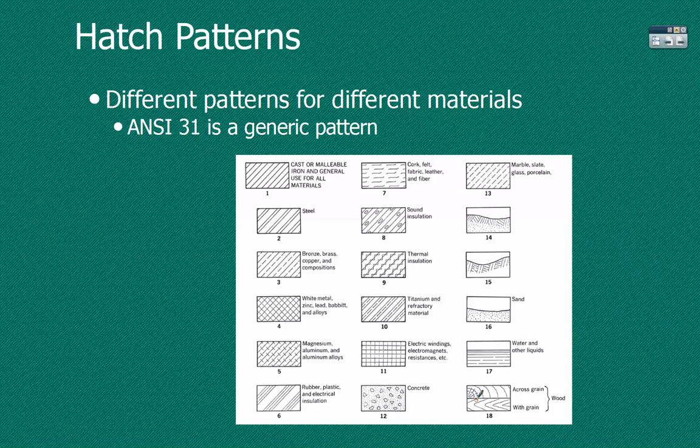For the width of the grain or the end grain, you'd just have to manually draw it. If you want to show that little drawing on it, you'd actually just have to draw that in. Questions? In Inventor, we can draw on top of our views. We can create a 2D sketch and just draw on top of our view. We're actually going to do that today.